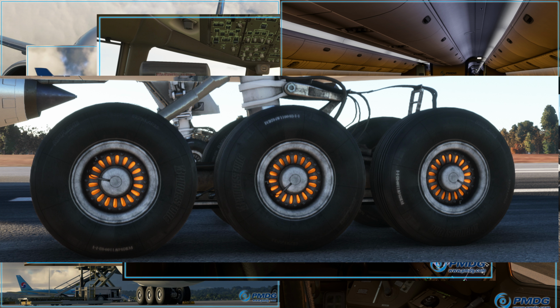constantly needs to press the pedals all the way forward, which can be a little bit difficult when you also have to use the pedals to control the steering of the plane on the ground, and when you are being thrown forward into your seat due to the G-forces, you might be thrown a little bit up and down because the runway is not exactly even. So normally the RTO auto brakes provide the best stopping performance, but theoretically the pilot can get a little bit extra deceleration out of the aircraft by going for maximum manual braking.